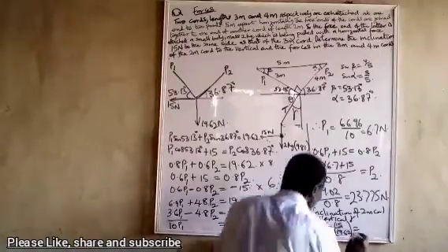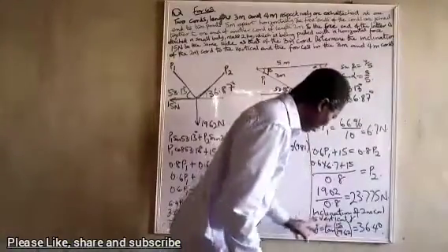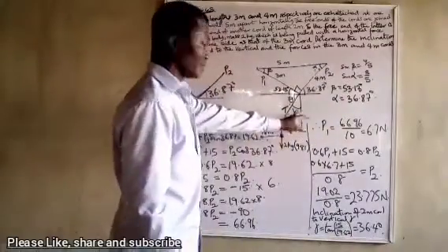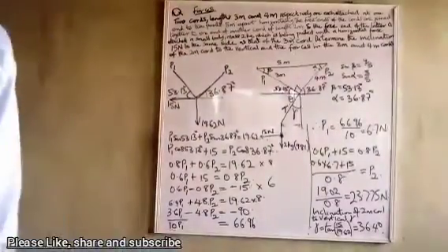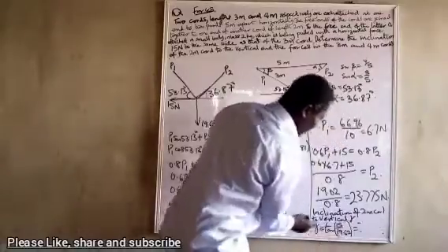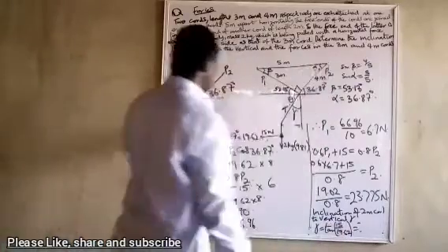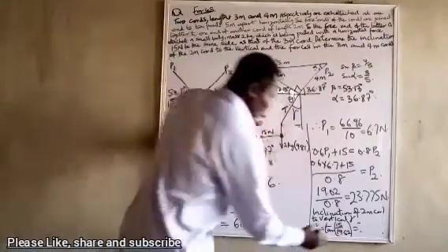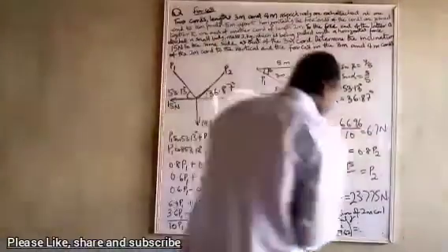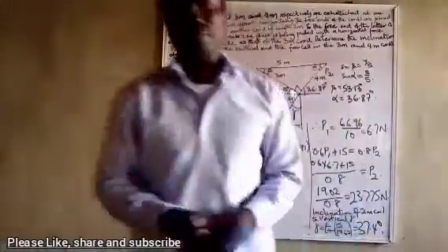Yeah, and that will give me. So the inclination of the 2 meter chord to the vertical, gamma, is arctan 15 over 19.62, and that's 37.4 degrees. This is the angle. Sorry, the inclination of 2 meter chord to the vertical is arctan 15 over 19.62. You remember the force, this one and this one, and that is 37.4 degrees.